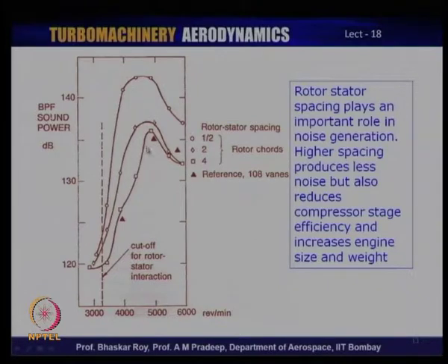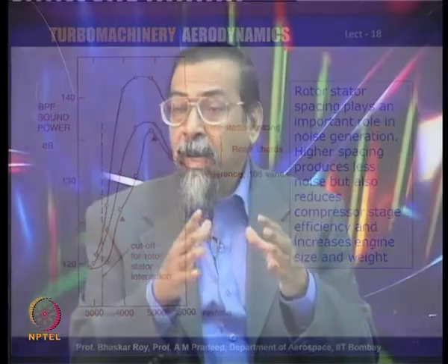The trouble is, if you increase the distance between the rotor and the stator, it is known that the noise would go down, but it would also reduce the compressor stage efficiency. That means the rotor and the stator would not then work as one single aerodynamic unit of a compressor, and as a result the efficiency of the compression would indeed go down.